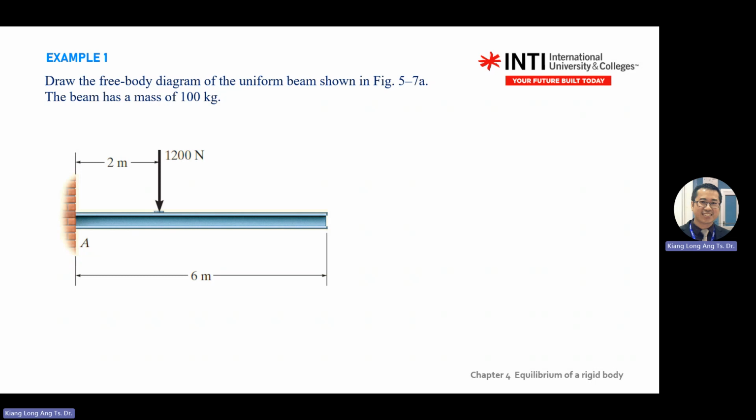It was inside the wall. So wall, you have what? Imagine what cannot be done by the object. So there are 2 forces at point A and then 1 moment at A. Again, moment, you can draw in any direction you like. It can be anti-clockwise, it can be clockwise. By standard practice, we will draw anti-clockwise following right-hand rules. So you have a positive value in your calculation.